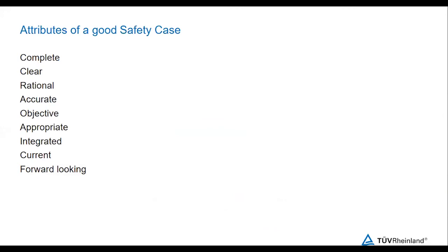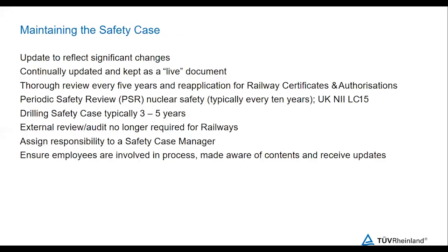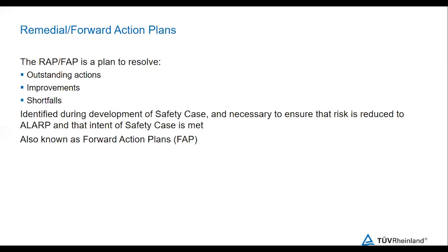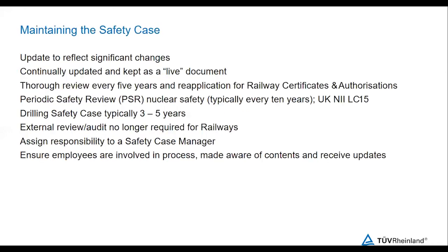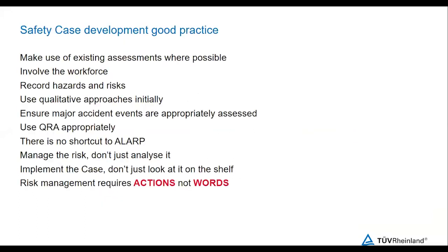Of course, the safety case must be complete, clear, and of course, must mention all the hazard scenarios that are expected. And of course, it needs to mention the way forward, what I shall do to keep my facility in the ALARP region. And of course, it needs to be periodically reviewed. There are a lot of drivers behind reviewing the safety case, either the update in the industry standards, in the company procedures, or modification in a procedure, aging issue. All of this makes us need to update our safety case.